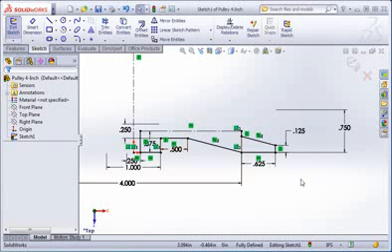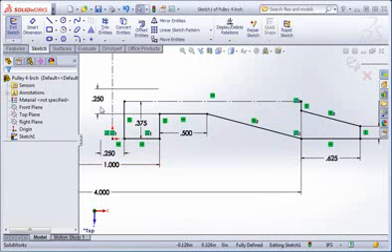The diametral dimensions are helpful because they define the overall thickness after the geometry is mirrored. For example, when this line is mirrored across the construction line, the new line will be 3/4 of an inch from the original. So this dimension defines the thickness of the pulley at this location. In fact, both the diametral dimensions on this construction line define the thickness of the part.